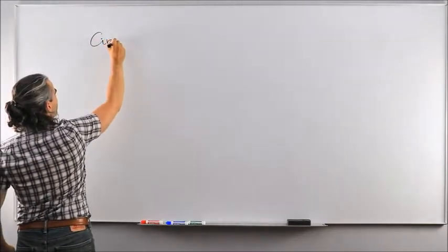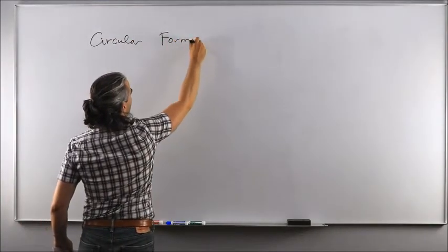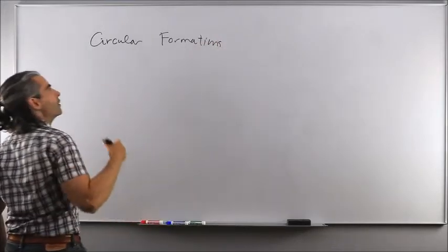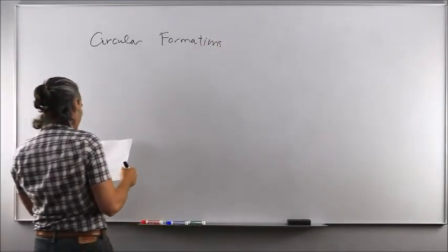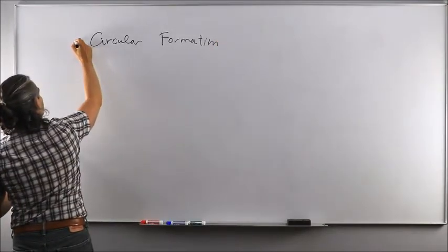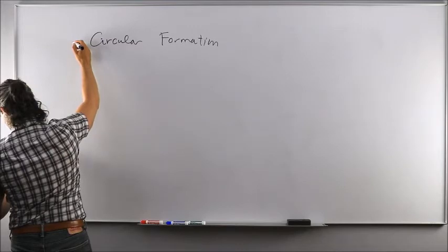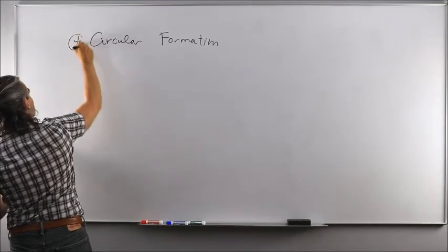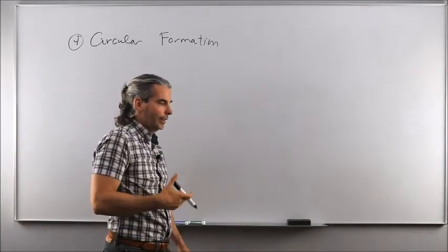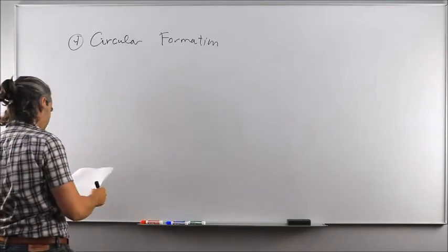So the third formation you can design just by looking at the initial conditions of the closed form solutions for the Hill differential equations. It's a circular formation. Is that the third or fourth? This is the fourth, actually. We had the in-plane ellipse, we had the along track, the in-track, 1, 2, 3, that's the fourth one, yes.